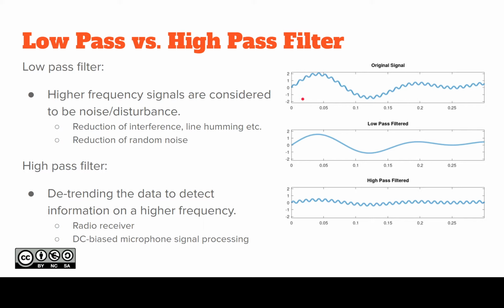This could be, for example, a sensor which gets a hit, and there's also some ringing in it. Maybe a piezo element put onto a metallic plate. When you hit it, you get that big warping of the metal plate, but in addition to that, there's that sound wave that gives that smaller, higher frequency component on it.